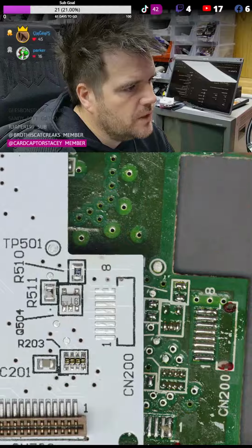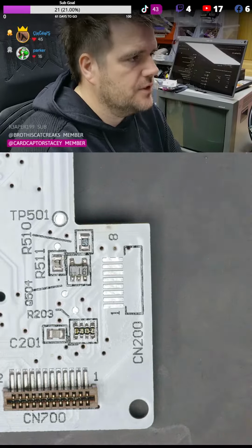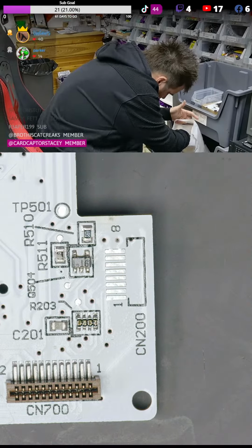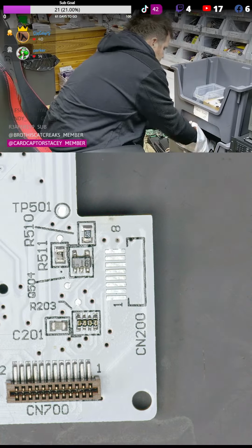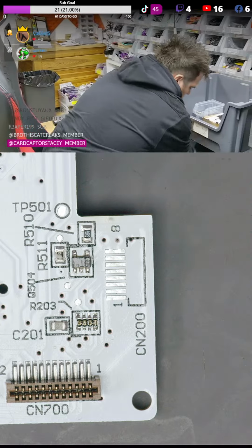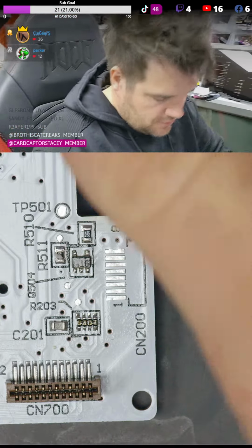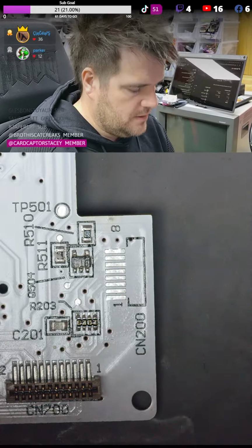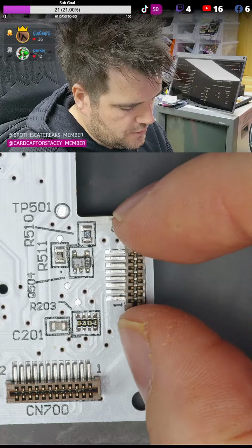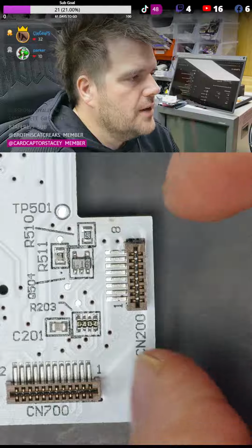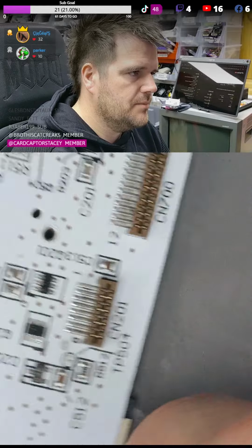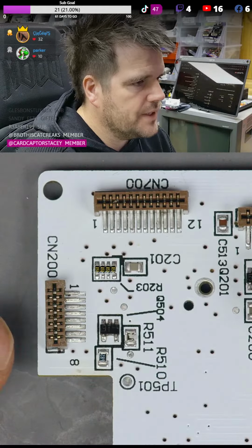Now that transistor's on, we can also hot air this connector on. So let me find that connector actually. There. So the only other part left from the customers is this connector. And I've got a spare box back. So the way I do these is to hot air from underneath, but you can also iron them. So considering I showed you how to hot air these ones on the last time, let's have a go at soldering this on with an iron.